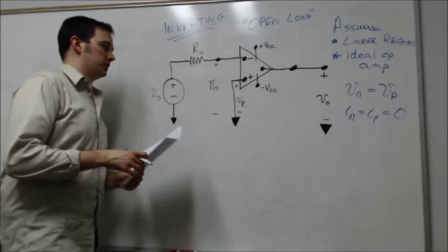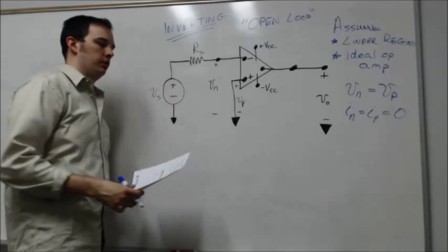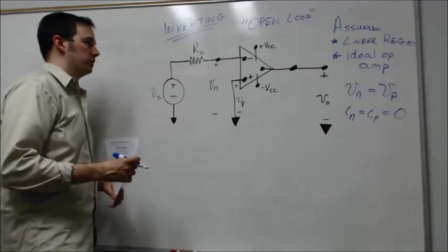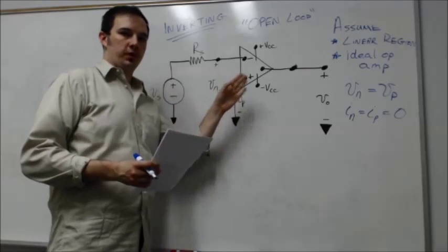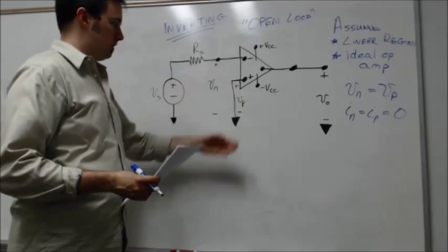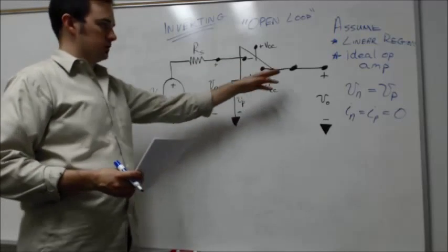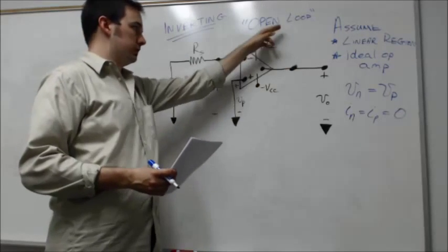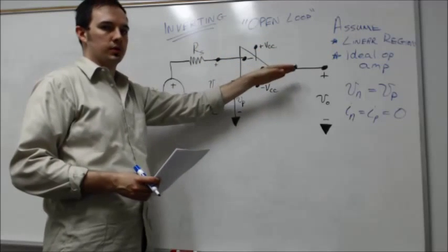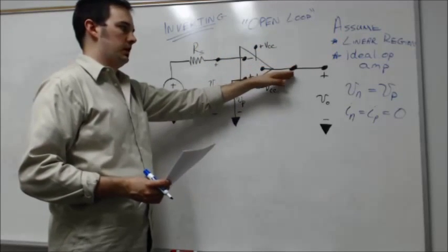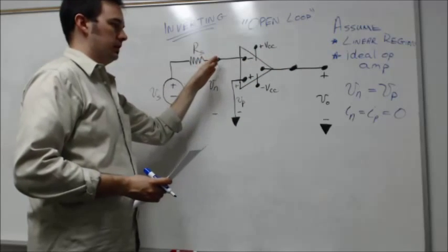All right, the little moving magic here again. So I've taken out all the things we worked on for that typical inverting amplifier circuit, and so now I still have the same fundamental circuits. We started looking at an inverted amplifier circuit, but notice the main difference here is that I've removed that feedback resistor. So now I no longer have that tie between the output voltage and the inverting input.